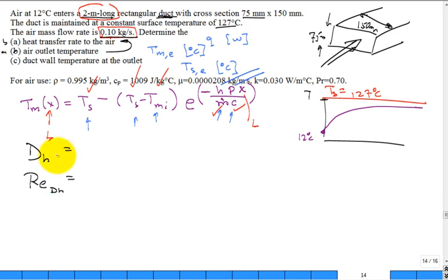Can I pause for a minute and you get the hydraulic diameter for this problem? And then if you get it, go ahead and get the Reynolds number. Sorry, I'm going a little slow. I only got about 10 minutes left. All right, so this hydraulic diameter, after you work it out, 4 times the cross-sectional area over the perimeter, comes in at 0.10 meter, true?